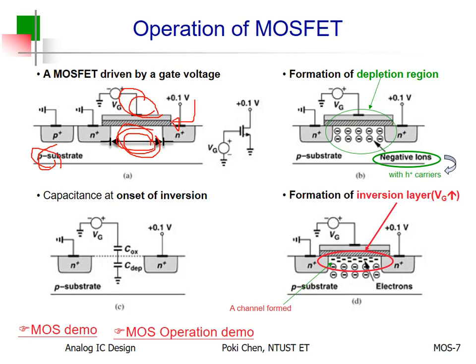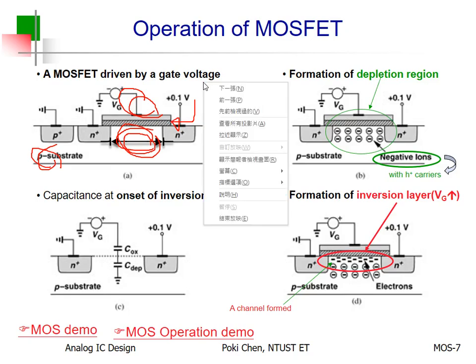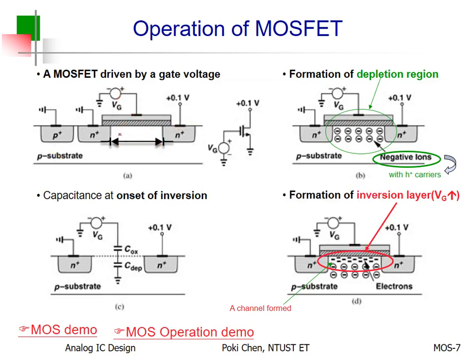Okay? So, yeah, people always say MOSFET is a capacitive device. Why? If it doesn't have such kind of capacitance, I mean between the gate and your substrate or your channel, as you like, then it doesn't work. It heavily depends on such kind of capacitor operation. Otherwise, it is not functional. Okay? So between the gate, the insulator, very important, right?